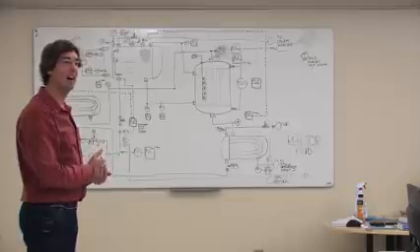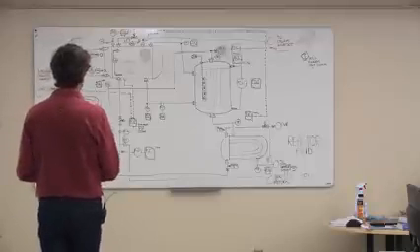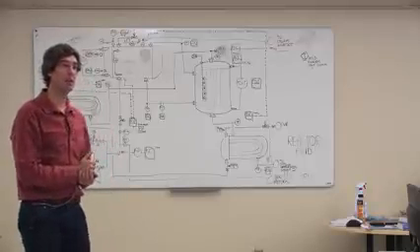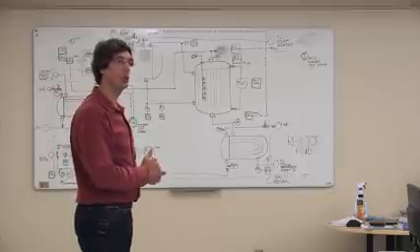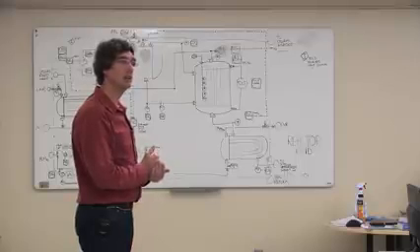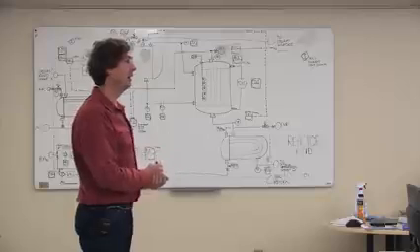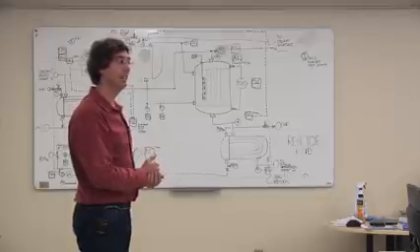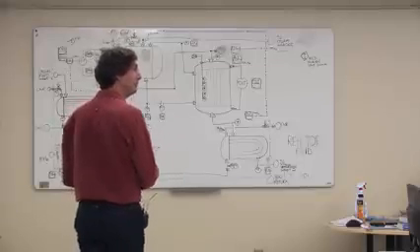If we increase the temperature, would that keep it as liquid almost? No, actually, increasing the temperature tends to cause stuff to scale out more. The solubility usually goes down with higher temperatures for some of those. Decrease the temperature, yeah, but the temperature is being controlled by the reactor. You don't have any choice over the temperature. Any other ideas? You're thinking about it at least. What else can we do?